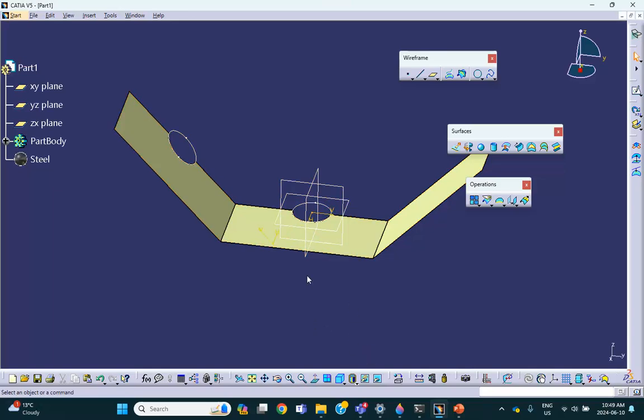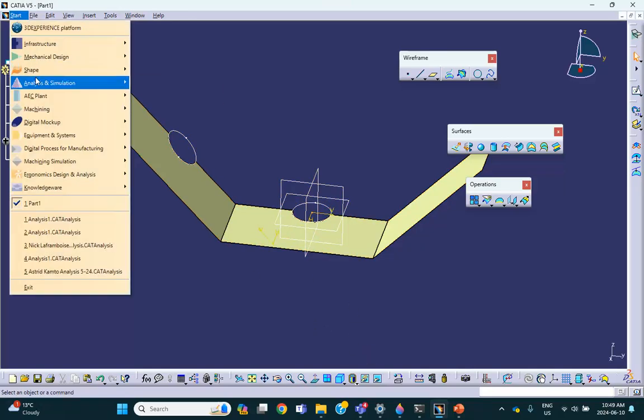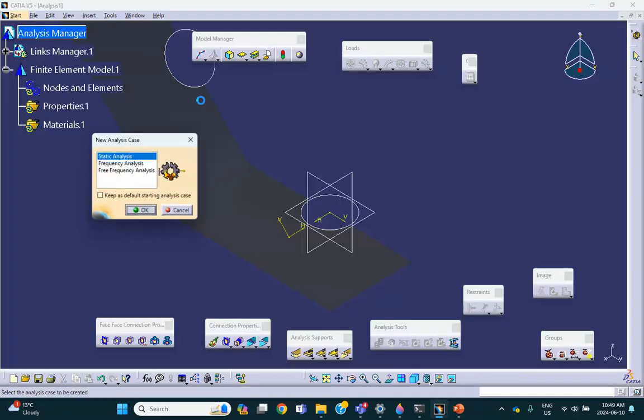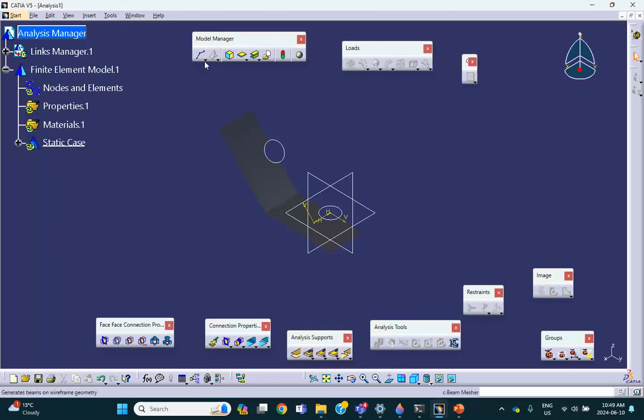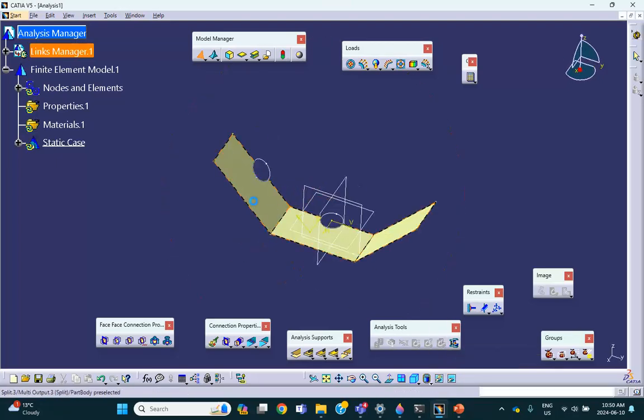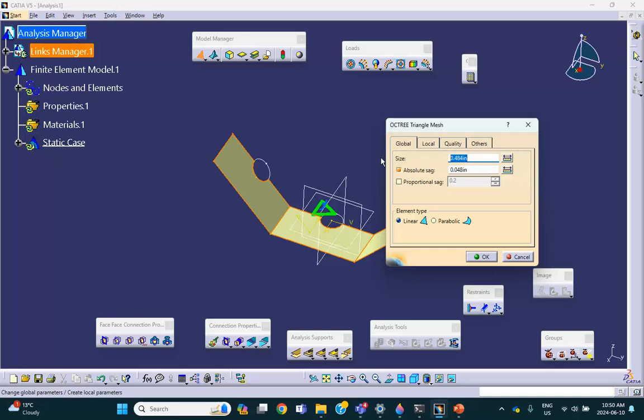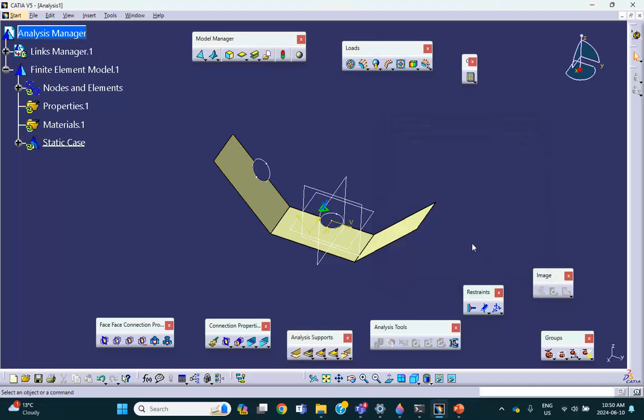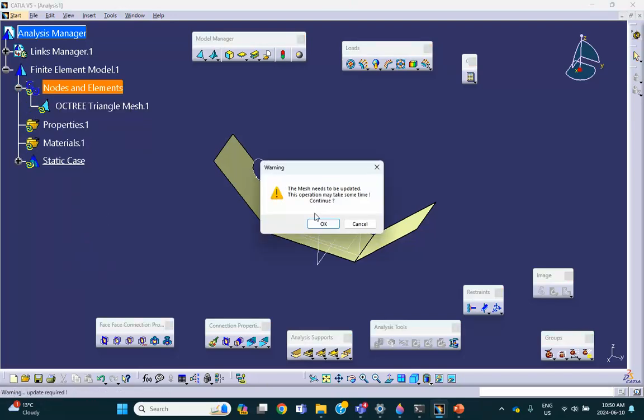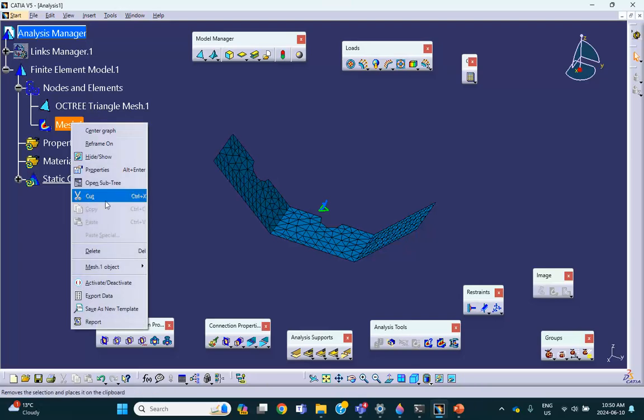And now we're going to go to analysis and simulation, generative structure analysis. We're going to use our good old, first of all, static, good old shell element right there. Let me change the rendering here, right there. See that? I select that. We make it smaller, maybe 0.2, but still linear. Yeah, good, that's good. And if you want, you can see the mesh. Right-click, mesh visualization right there. I'm going to deactivate it.